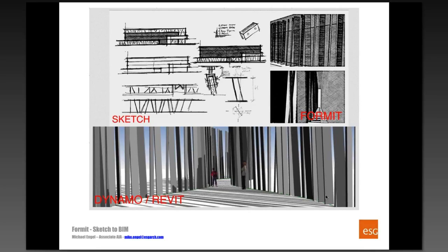And then taking components in Revit and saying, let's use Dynamo to study what it means as I rotate those. How many different ways can I rotate them? And not being limited by one decision of one person going through and rotating each of those to some angle, but letting the computational side of the software iterate and potentially get the best and most effective solution.